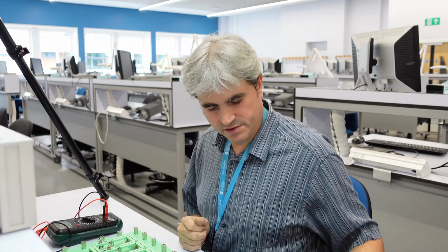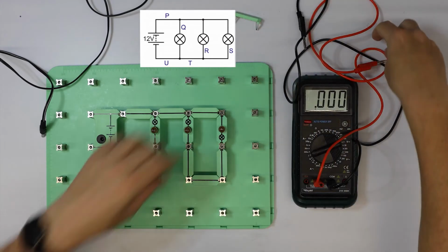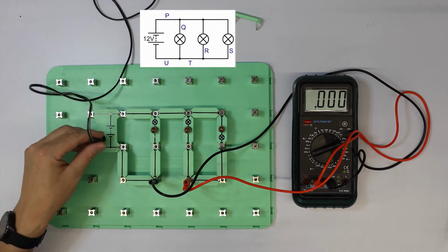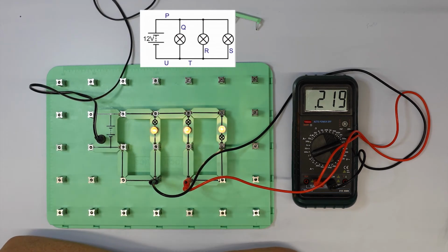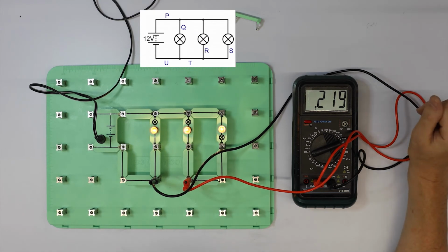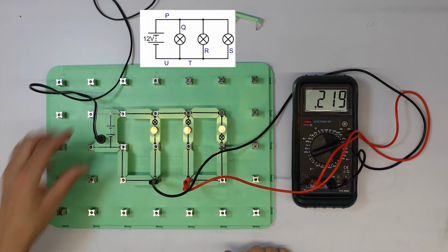So we just have 2 measurements to go. We have measurement T and measurement U. So T is at this location here. So I'm going to connect these two and connect the power. Okay, so interestingly now we have a value shown on the multimeter of 0.219 amps or 219 milliamps. So we can take a note of that. So that's twice the value in each one of these circuits and 2/3 of the value that we had in our first measurement as well.